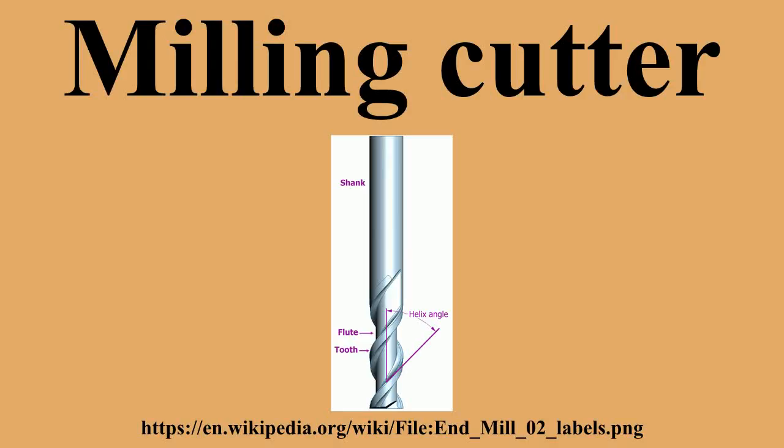The right tool coatings can have a great influence on the cutting process by increasing cutting speed and tool life, and improving the surface finish. Polycrystalline diamond is an exceptionally hard coating used on cutters which must withstand high abrasive wear. A PCD-coated tool may last up to 100 times longer than an uncoated tool. However, the coating cannot be used at temperatures above 600 degrees Celsius or on ferrous metals.